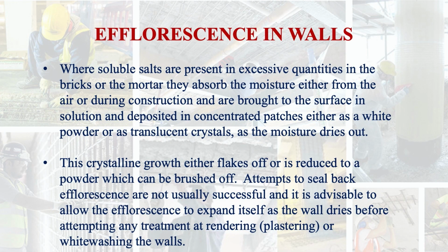So, this crystalline growth either flakes off or is reduced to a powder which can be brushed off. Attempts to seal back the efflorescence are not usually successful, and it is advisable to allow the efflorescence to expand itself as the wall dries before attempting any treatment at rendering or whitewashing the walls.